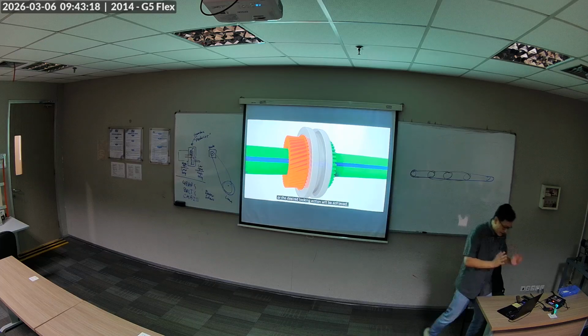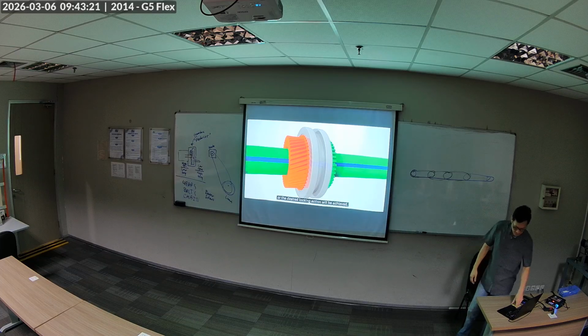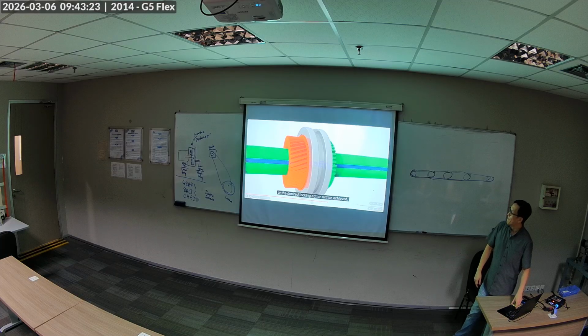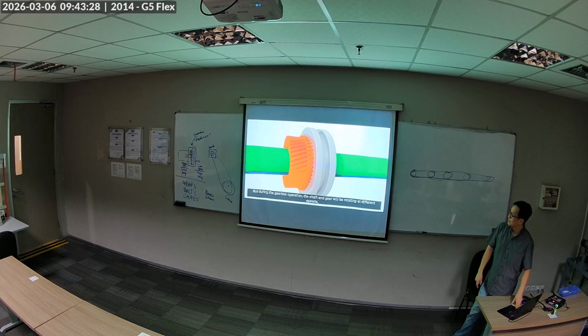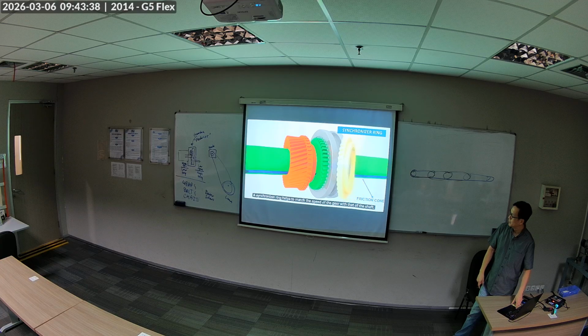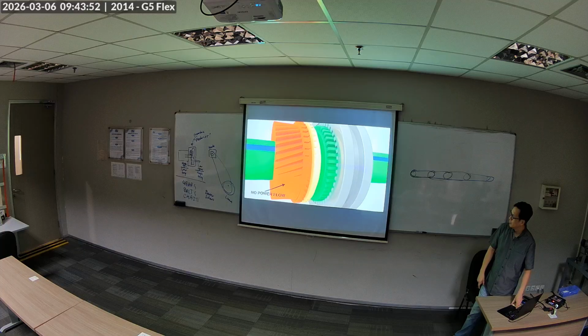The question is, it's not that simple because there is a speed difference. The desired locking action will be achieved, but during the gearbox operation, the shaft and gear will be rotating at different speeds, so such a locking action is not an easy task. A synchronizer ring helps to match the speed of the gear with that of the shaft. The synchronizer ring is capable of rotating along with the hub, but is free to slide axially. Before moving the sleeve, the clutch pedal is pressed. This way, power flow to the gear is discontinued.